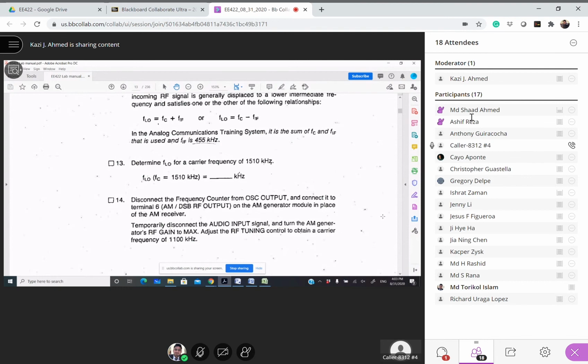This is how, when you change the local oscillator, you can pick different carriers, meaning you can pick different channels, right? So you have all the channels there. You just change the local oscillator and get it tuned to a particular channel, meaning the relation has to be FC plus IF. Whatever FC is there, if this relation holds, then the receiver is tuned to that particular carrier, and now it's receiving signal from that particular carrier only. Other channels are blinded. You can't hear other channels anymore, right?